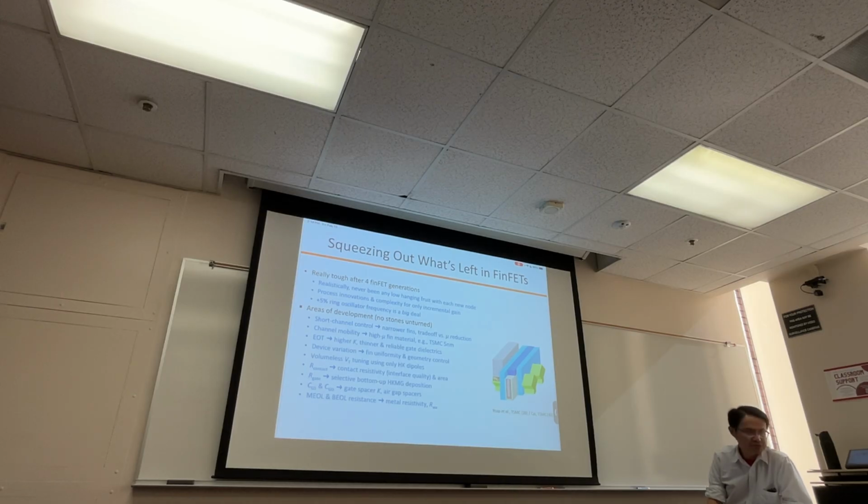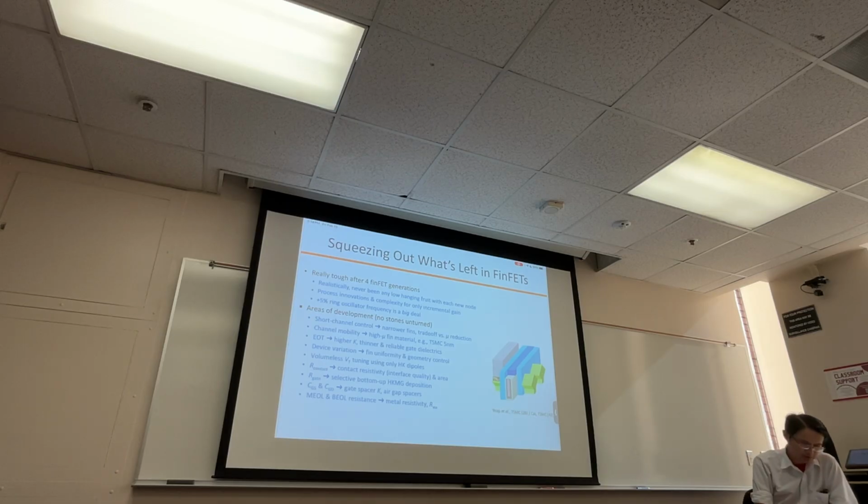Is very resistive, right? So they have still been trying to improve that, here and there, like the gate resistance. They try to improve the CGS and CGD. Remember we talked about the large parasitic capacitance, right? So those engineers continue to improve that, but it's just that at some point, you're going to meet some limitation.